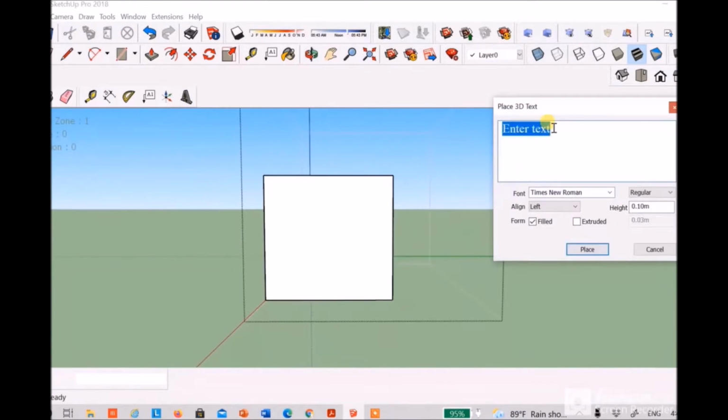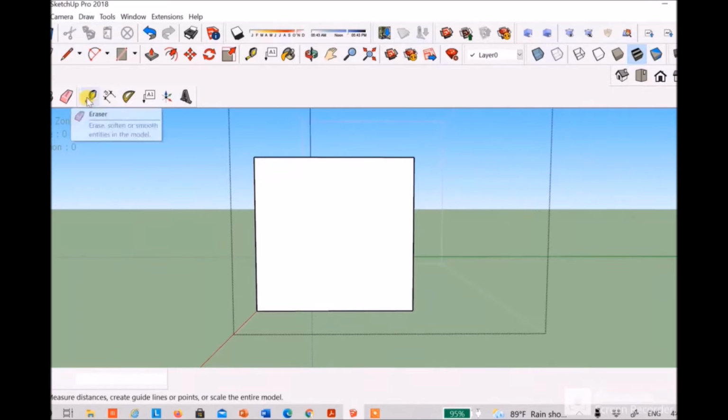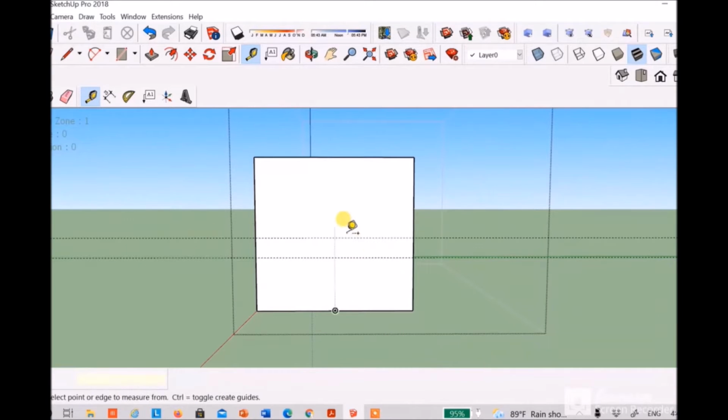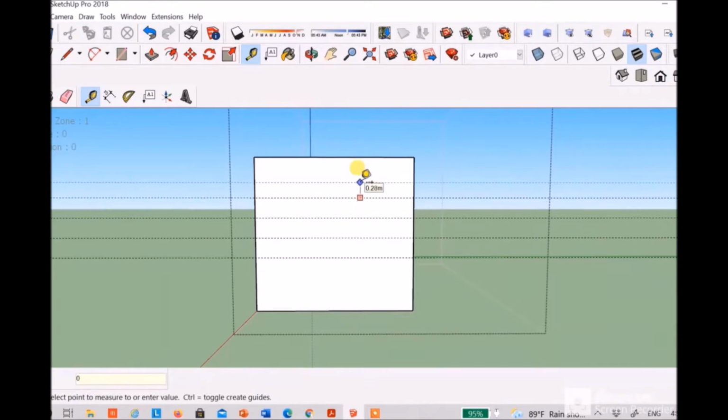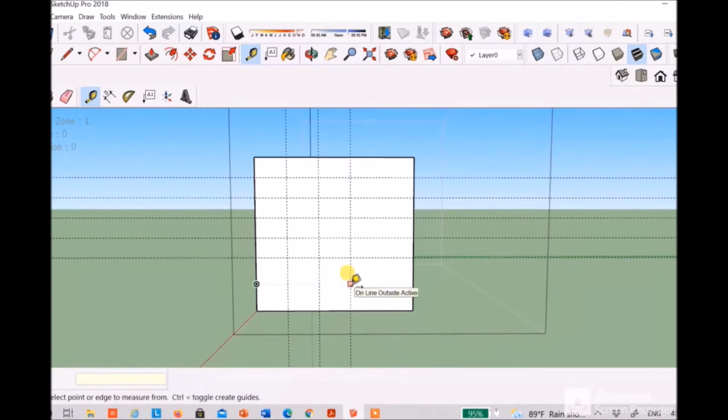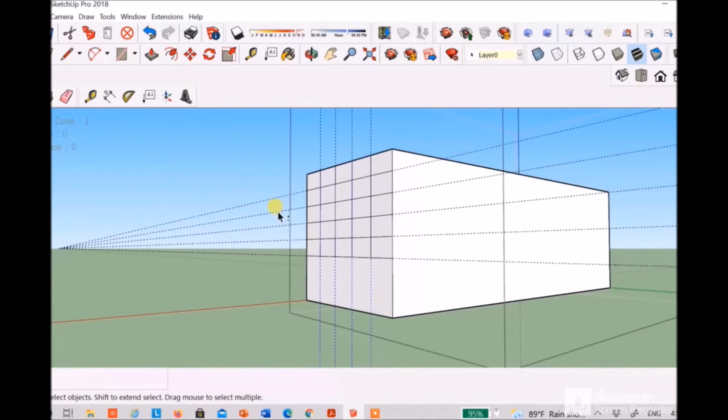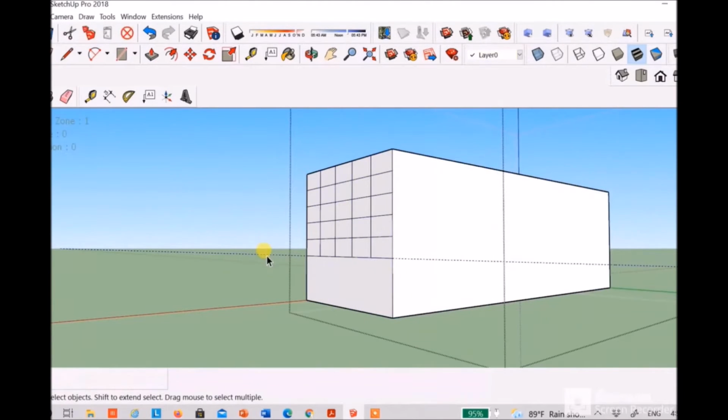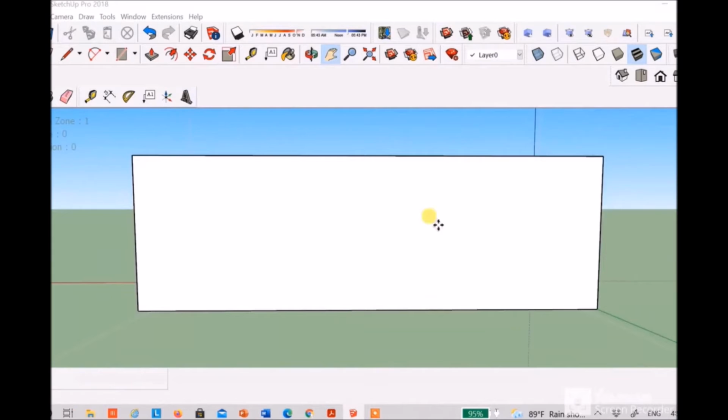Next we proceed to the east facade and give the name wall 3 to this section. This wall has 26 sections with 5 horizontal divisions of 0.37 meter each and 5 vertical divisions of 0.6 meter each, and we have the 1 meter height from floor to work plane. After drawing edges and removing the extra lines, we proceed to the other side, which is our north facade.